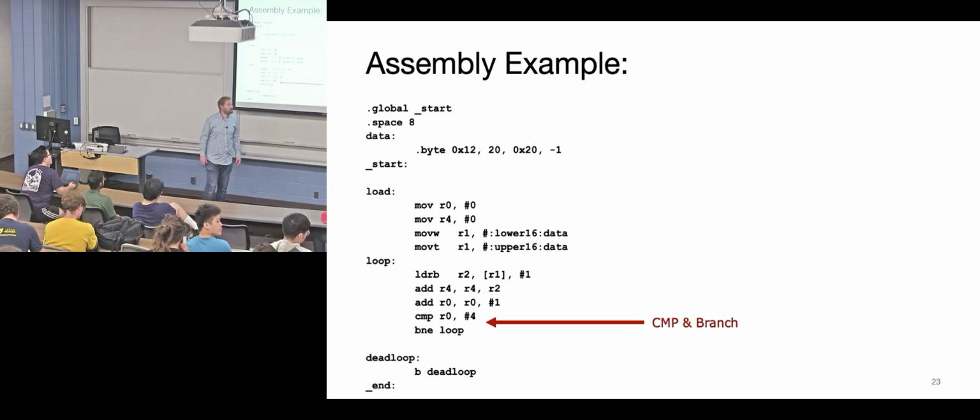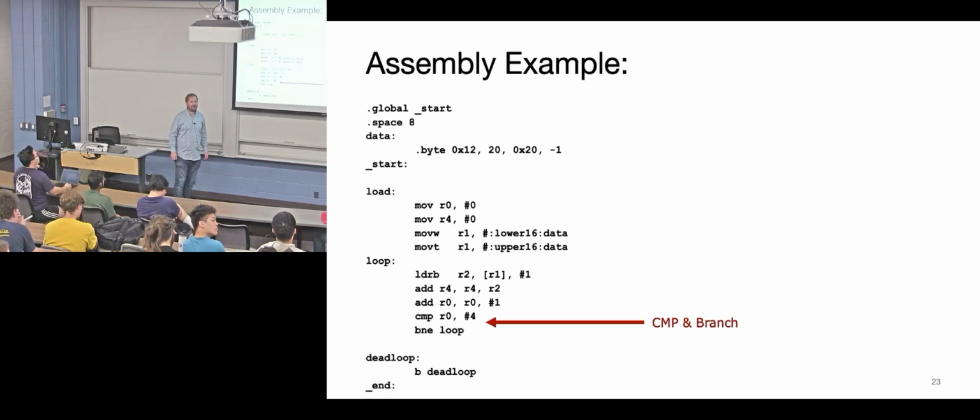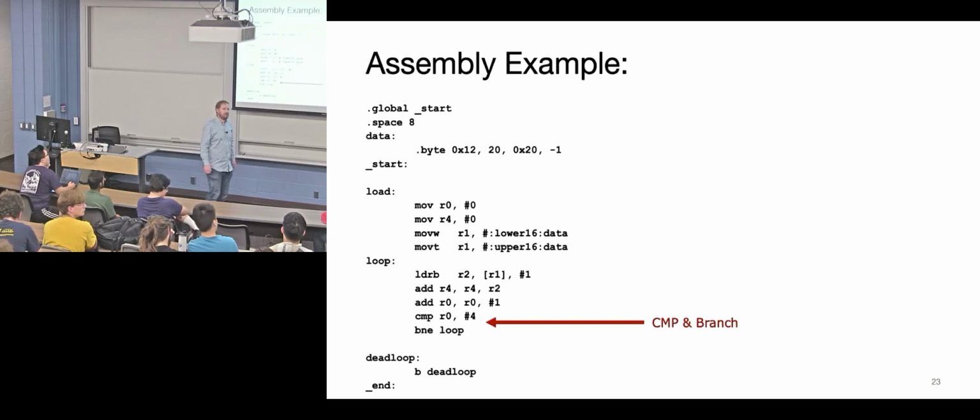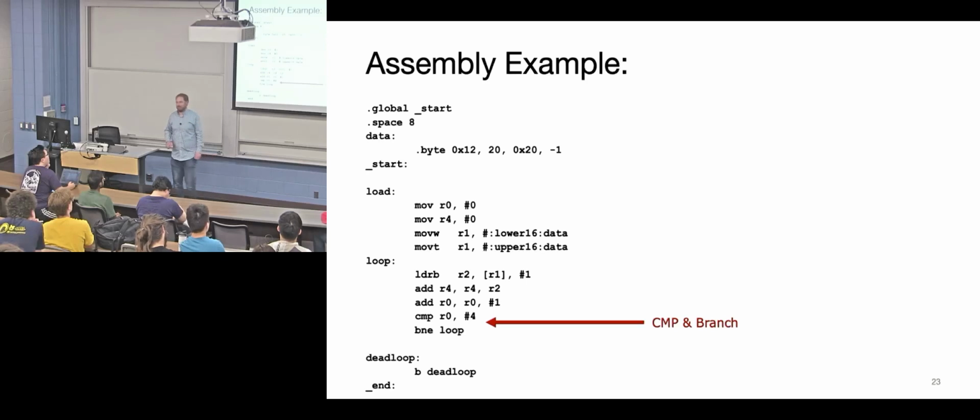So when we're using -1 with byte, are we filling those 8 bits with all ones using 2's complement, or how are we signifying it's a negative number? 2's complement. Yep. But the actual bits are just set to 1, and from other perspectives, it's just 8 ones. Do we always work in 2's complement? Well, your assembler, seeing that you denoted that to be -1, is going to put it into 2's complement. So if I said 0xFF, it would have the same result. Yes. Right. Good.